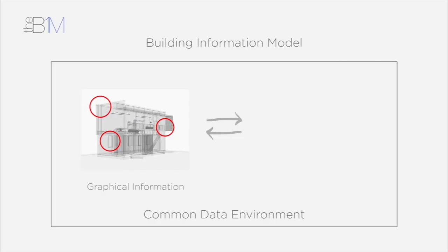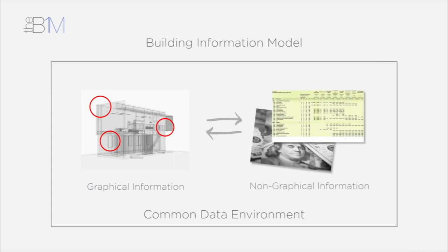It's what we call 5D BIM, where we've taken the three-dimensional model, we've appended cost information to it, and rapidly produced estimates. The big change for quantity surveyors is we're now free to do higher value added work, such as validating the information in the model, verifying that scope has actually been captured in the model itself, and supplementing the quantities extracted from the model with items which may not necessarily have been modelled.